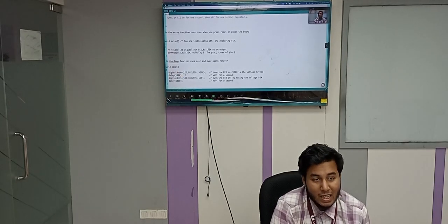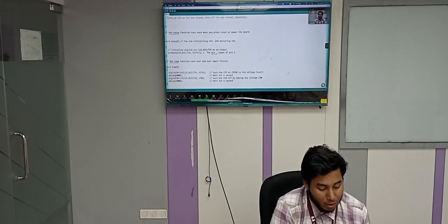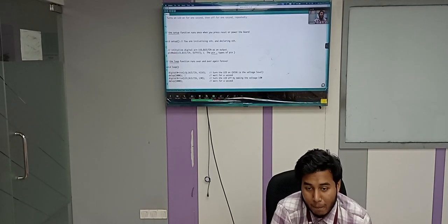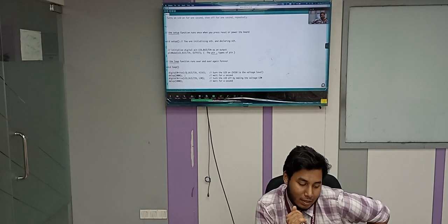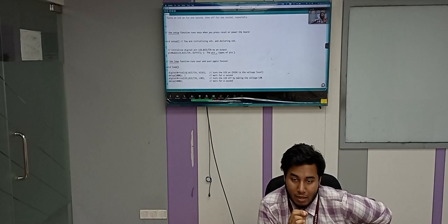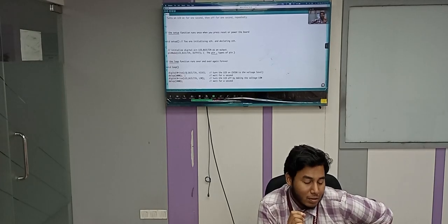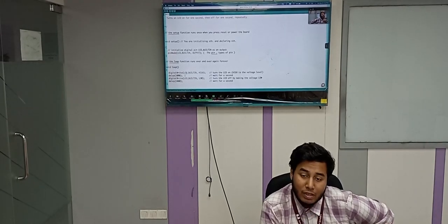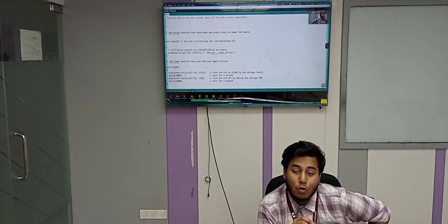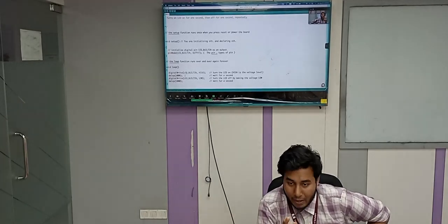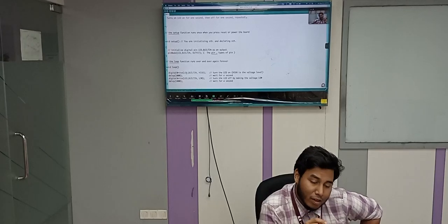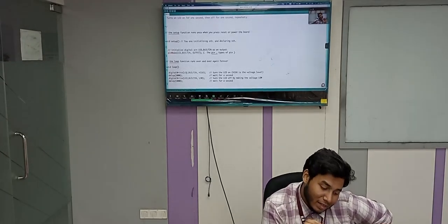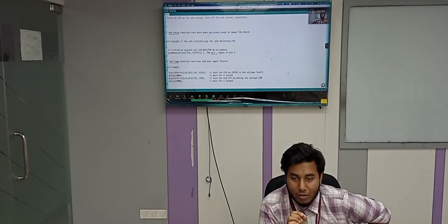Okay, fine. So that's the section over there, and you have to set a delay of 1000. Delay means a wait. So 1000 is just for a second. If you want to turn off a light for a second, you have to set 1000. Why 1000? Because 1 second equals 1000 milliseconds. So the delay function has been built internally as a millisecond function.